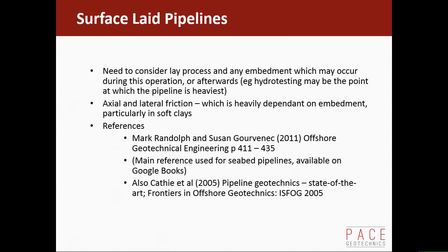That one is quite good for surface laid pipelines, and easily accessible. It's on Google Books if you go onto there and go to those pages. I've certainly always managed to find it on Google Books when I go in, but you maybe don't want to do it too many times because it does lock you out. And that's a paper probably best for trenched pipelines if you want to look at that. I've also got some references at the end which I'll mention, but there's a DNV document which is pretty good as well.